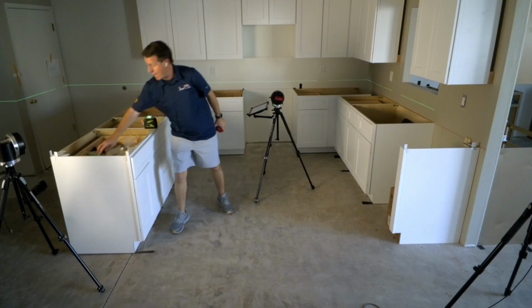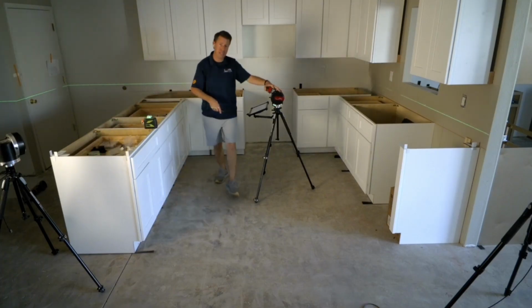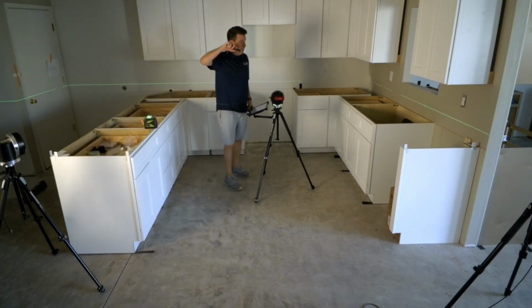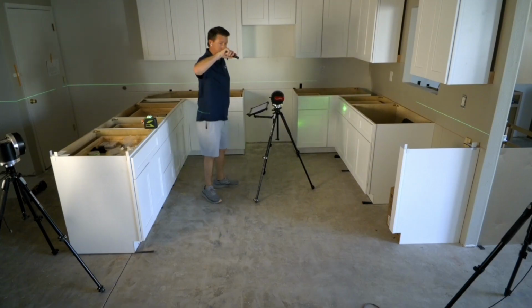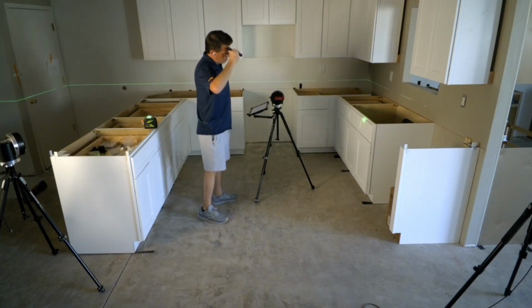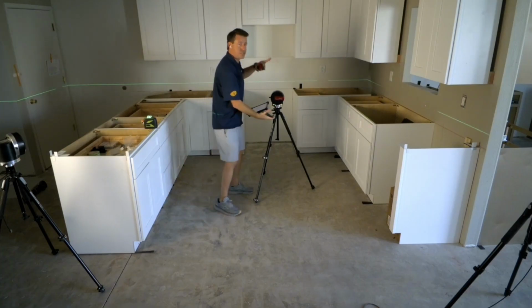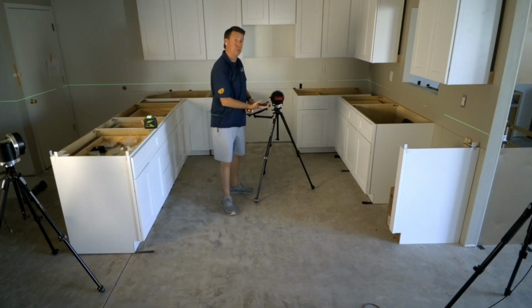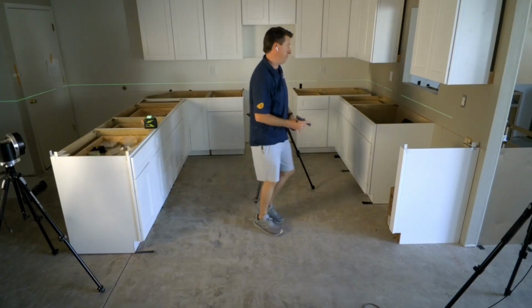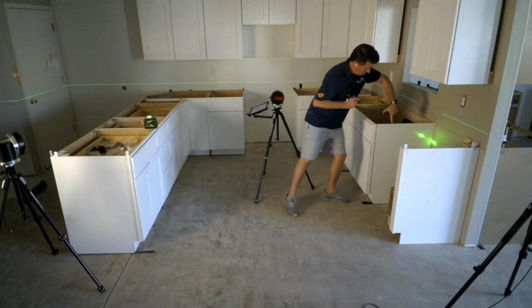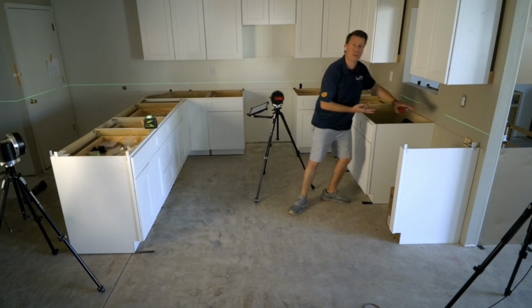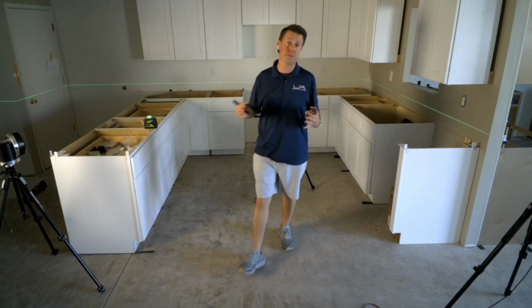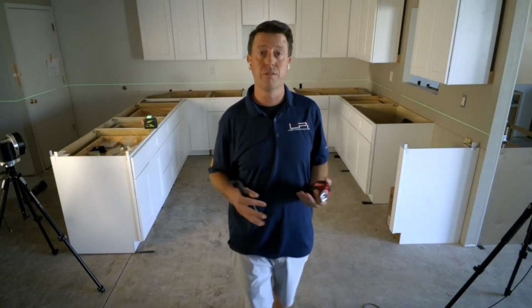So as we use the LPI laser to capture, and I'll use this bright green pointer laser so you can see on the video, we could either measure points on the cabinets or up in the walls, and the system will flatten everything to the plane that we're about to set, right? Whether we're up here or down here, it'll compress all that to our flat surface that represents, in most cases, the surface of our stone.